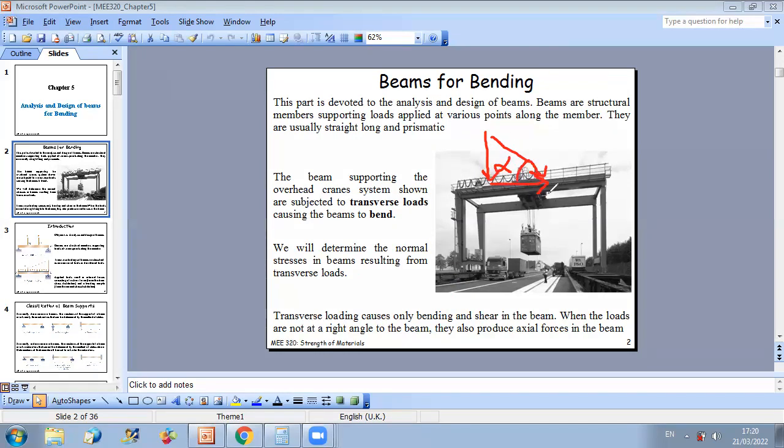So if the load has an inclination with respect to the beam, it's not perpendicular to the beam, then we decompose it into a normal component. The normal component will lead to normal stress distribution. Okay, and already we know that the bending moment is also created by normal stress distribution. This is why we'll see after how to do superposition of all of these effects.